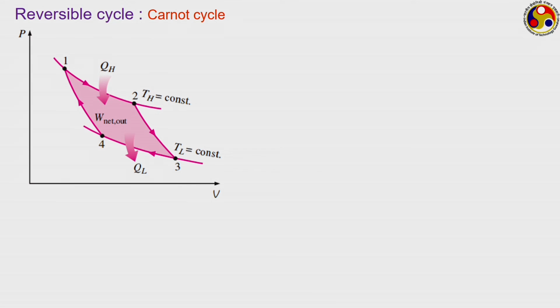The most common cycle that we talk about as a reversible one is the Carnot cycle, which is again an idealization, but it is possible to have any other kind of reversible cycles also. In a Carnot cycle, we generally consider 4 processes to constitute the cycle. Process number 1, from point 4 to 1, is an adiabatic and frictionless process. So, during this process it is frictionless, so internally reversible, and also adiabatic, so externally reversible. Therefore, this 4 to 1 is a perfectly reversible or totally reversible process.